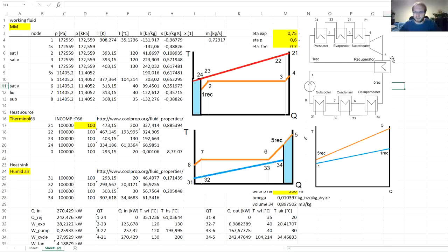So that means for the same amount of heat transfer, which is the same for both sides of the heat exchanger, the fluid with the lower specific heat capacity will undergo higher temperature change. So this line will be steeper, while the liquid fluid with the higher specific heat capacity will undergo lower temperature change over here. So it translates into the fact that the minimum temperature difference has to be here at the low temperature side of the heat exchanger.